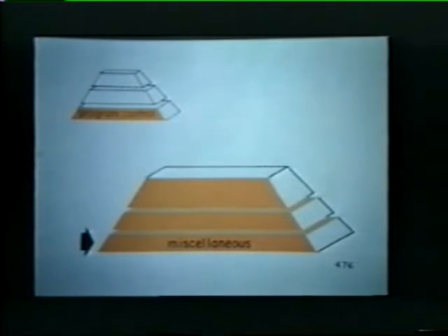Both traps and interrupts first save the current PC and PS of the main program by pushing them on the stack, then find the required handling routine by means of a vector. Finally, once the routine has been completed, return to the main program is accomplished by either an RTI or RTT instruction, which pops the program PC and PS off the stack. Now, let's discuss the very last group of program control instructions, the miscellaneous instructions.